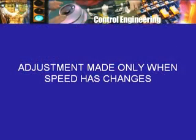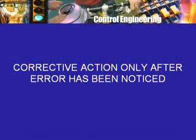then there is nothing that we have to change, which means that we will have to make changes, either the human being, operator, or automatic device, the controller will have to make changes only when the speed changes, the speed is no longer at the desired value, or the tachogenerator output voltage is no longer at the expected value of 20 volts. So this means that you can take corrective action only after an error has resulted and been noticed.